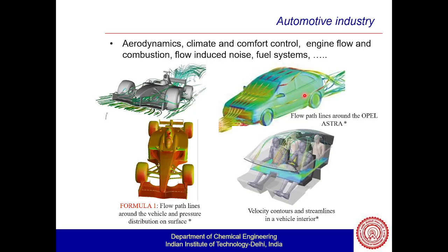So you have to check the mass conservation, the momentum conservation, and multiple things inside it to get a good picture. Also check whether the velocity or the pressure is unphysical in nature or not. Those are the things I will concentrate upon.